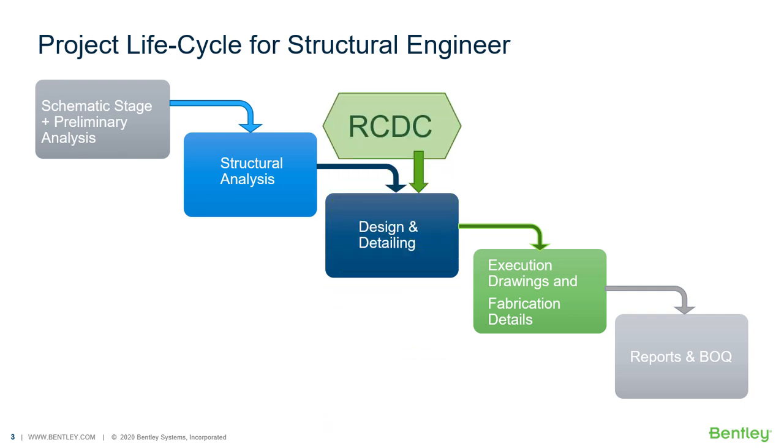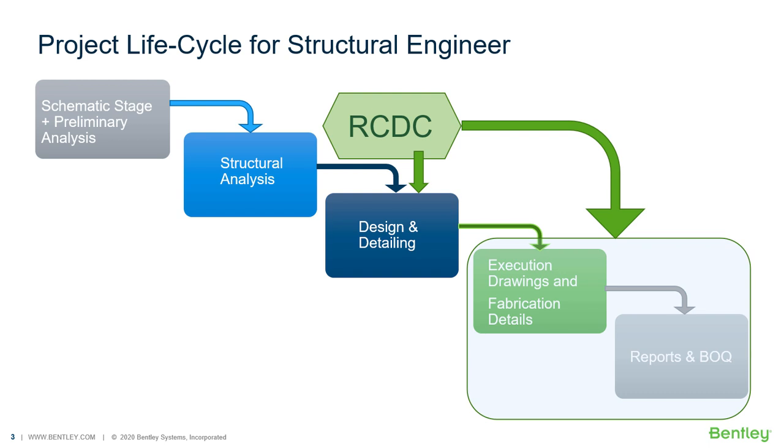RCDC actually handles this portion. So post analysis, it allows an interactive solution for clients to finalize the design and detailing together. And this is an important thing. It is not that you complete the design and detailing is a separate activity. It is together. And once that is done, further outputs, whether it is drawings or calculation reports or BOQ, is combined. All of that in one go. And that is how RCDC fits into a project cycle.